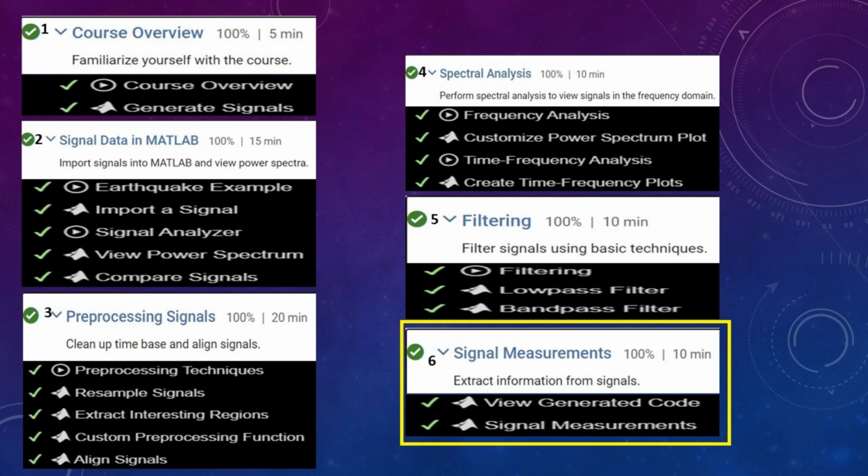B. Signal measurements tasks. Tasks: modify the spectrogram code to add output arguments. Calculate the sum and power of the spectrogram, plotting them over time. Use the Find Local Extrema task to detect earthquake timestamps based on the power plot.